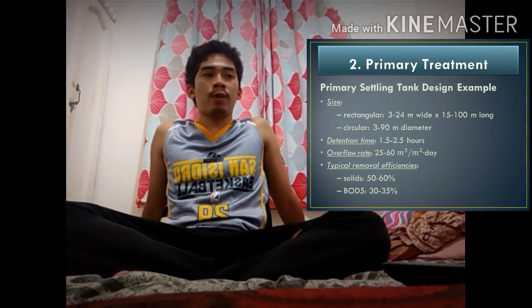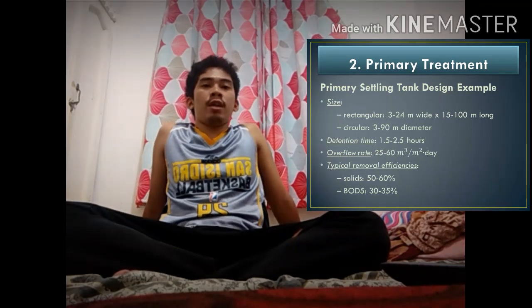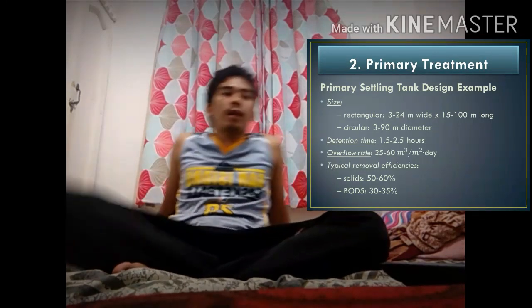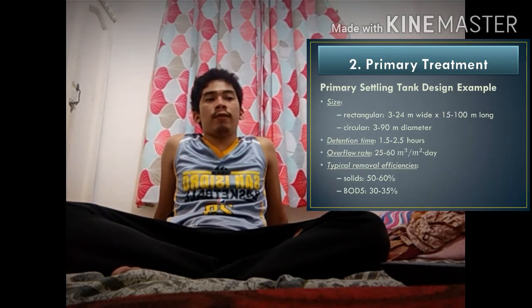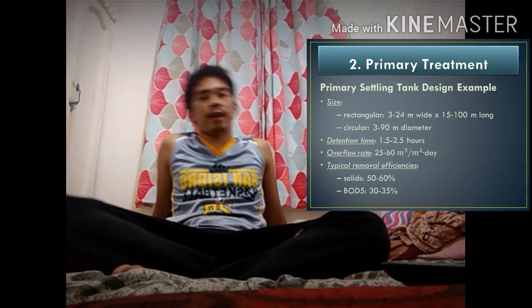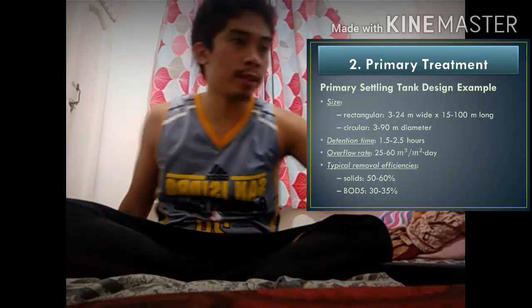Its detention time is 1.5 to 2.5 hours, with an overflow rate of 25 to 60 m³ per m² per day. Typical removal efficiencies are 50 to 60% for solids and 30 to 35% for BOD5.